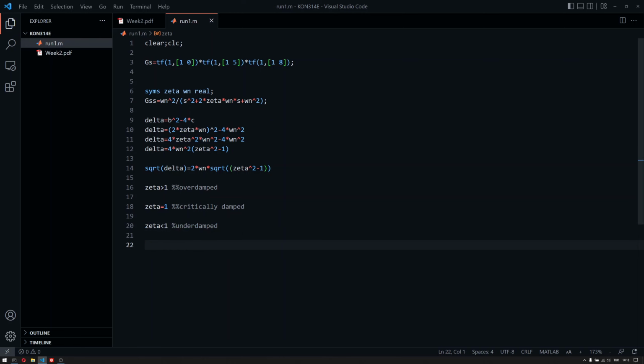There we go. Now in this case we will have complex conjugate pairs. In this case we will have identical poles and real poles. In this case we will have real poles. These two will not overshoot because they have real roots, and therefore overshoot will be 0. Here we will have some overshoot, and we will see how to determine that. And yeah, that's basically it. That's what we need to know here.